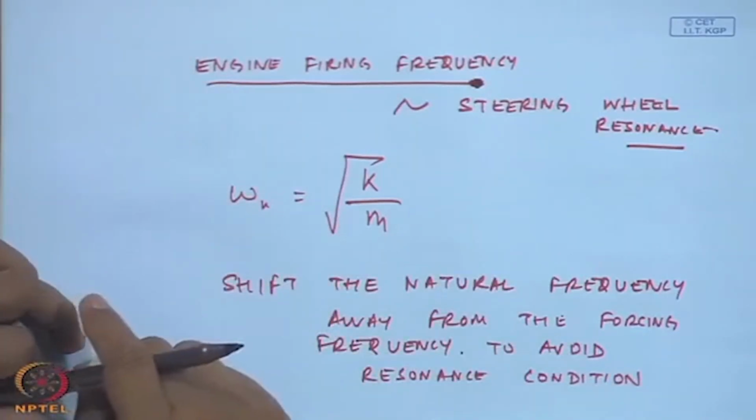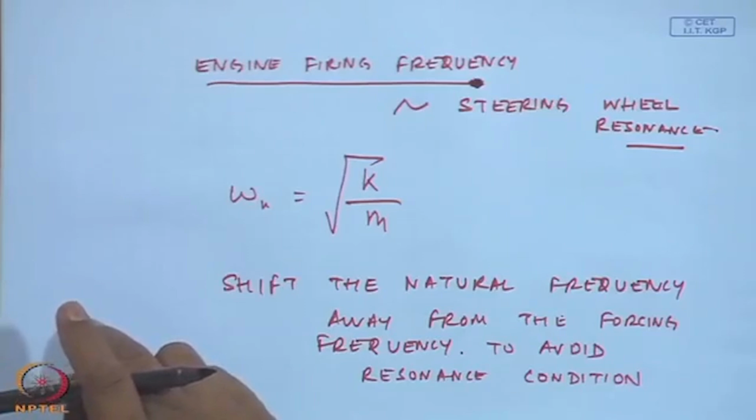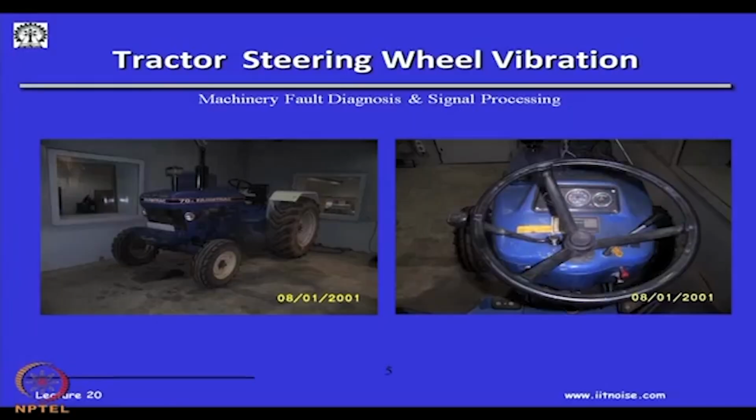Okay. So, now how do we do the vibration monitoring here? Of course, you do not see these accelerometers. If you see the clips, there are locations. Sometimes you can even mount accelerometers on clips. For example, this is the plastic cover on the steering wheel skeleton. Okay, as a molded plastic, wherein we can put a clip on this, and on this clip you can mount the accelerometer. Okay.